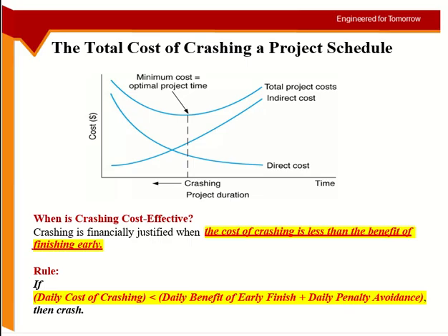So if I reduce the project to 9 days, I will hire extra labor to finish it 1 day early. But at the same time, you will have less extra cost for electricity and water and office and stationery and transportation. So this is what is happening here. Okay, on this side, direct cost is increasing, indirect cost is reducing.